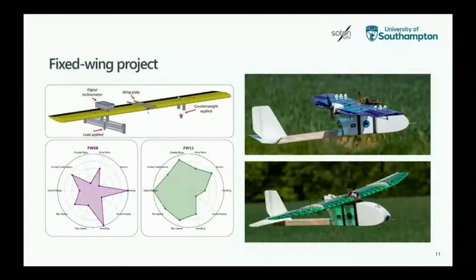We then also find the flexural axis, and then we hang a mass forward of it, and we see how much it twists. So then the students have an idea of how much the wing bends and how much it twists. And then the students get graded, and we have these radar plots where they can see the different attributes of their design for their final score.